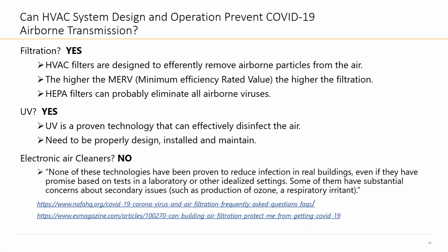if HVAC filters are designed properly, placed properly, installed properly, and there's no bypass, theoretically they can help remove airborne particles from the air. And we have a sense that typically, the higher the MERV or the higher the efficiency, the higher the filtration. And HEPA filters, as you know, can remove almost all airborne viruses. They have a very large 99.9% efficiency.